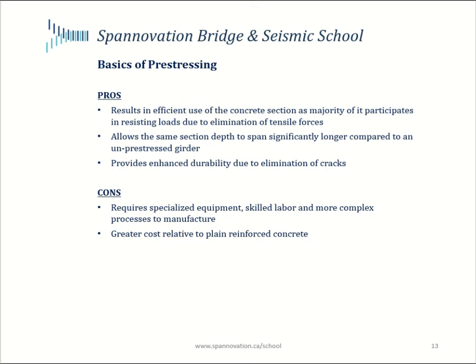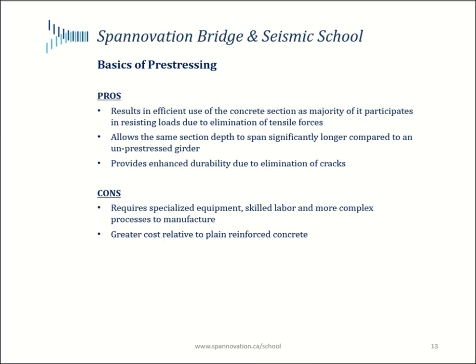So it does require a certain level of skill and, of course, more complex processes and quality control processes to manufacture relative to plain reinforced concrete. In conclusion, you can say that pre-stressed concrete starts to gain an advantage when the higher cost of its production compared to reinforced concrete is offset by the economics of its material efficiency and long-term durability.